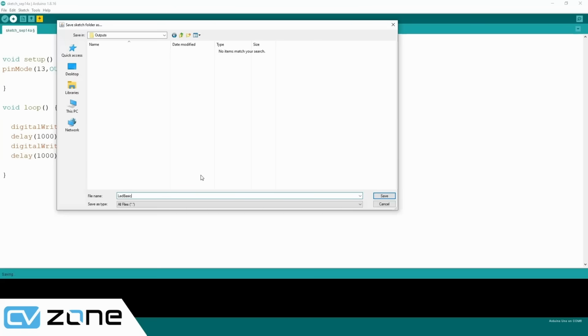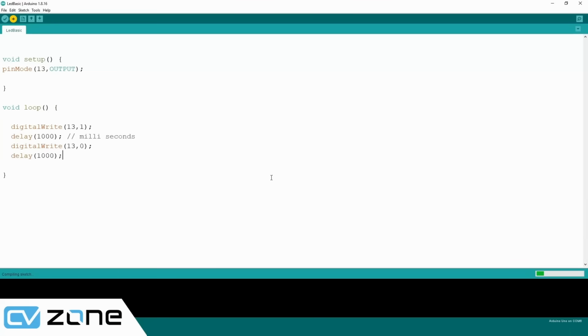For each input or output, we are going to look at the basic code, and then at the code that will allow us to do serial communication with the Python code. This basic means if at any point you are facing any issues, you should come back and check the basic code. If the basic code is working fine, that means the hardware is fine and there's an issue with the software. This is a very good idea whenever you are using different sensors.